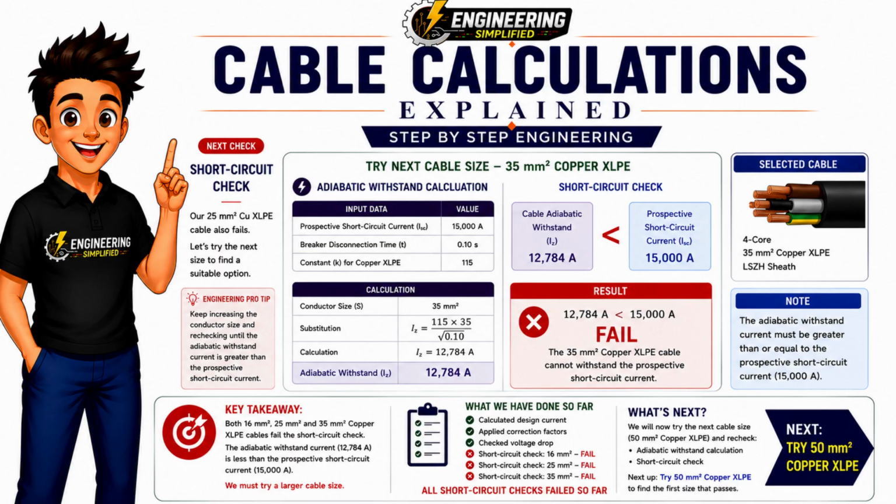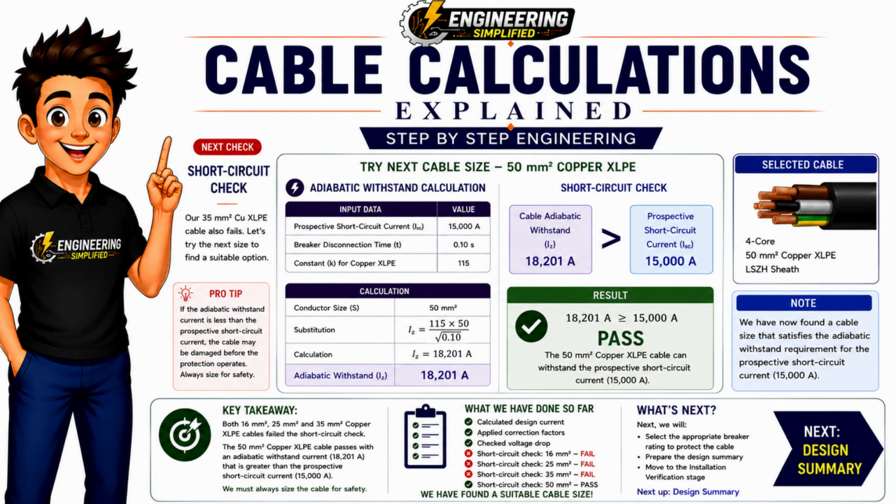Repeating the same calculation gives an adiabatic withstand current of 12,784 amps. Although this is an improvement, it is still less than the required 15,000 amps, so once again, the cable fails the short circuit check. This demonstrates an important engineering principle. Just because a larger cable carries more current doesn't automatically mean it can withstand the required fault energy.